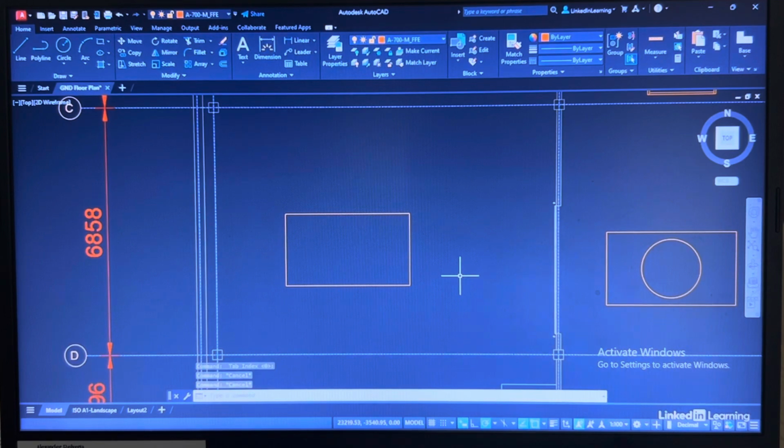But you can see there how polar tracking and ortho can work well together and also individually. I would say the majority of the time though, utilize your polar tracking, but if you are constrained to horizontal and vertical for a specific project, put your ortho on.